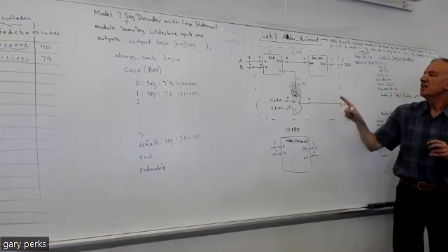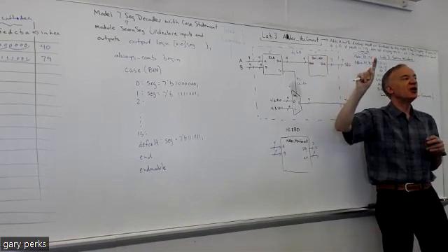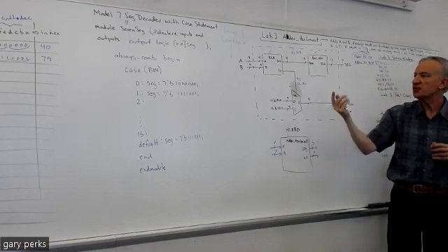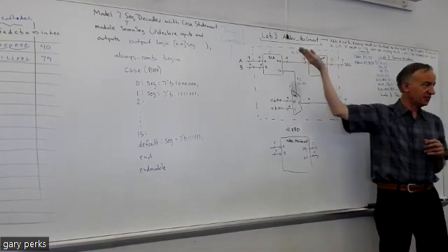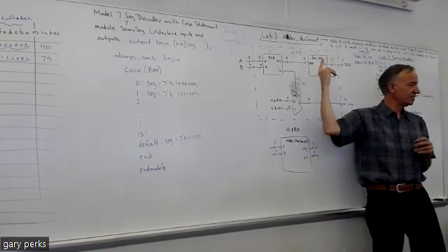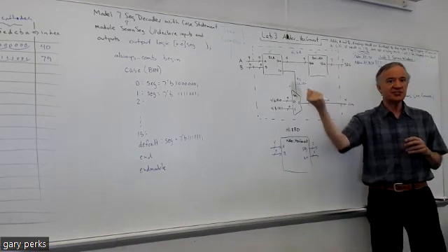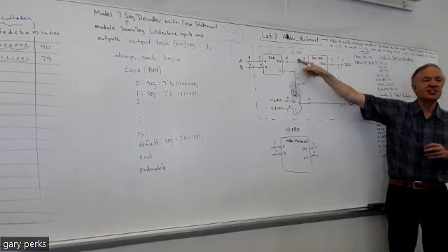Oh, the other thing is, because the internal signals for the RCA were all a single bit, right? When you declare your internal signals, and remember the way you do that is after you declare the inputs and outputs for the overall structural model, then you do logic. You define your internal signals with logic. Okay, well, what's different about this internal signal? It's 4 bits. Yeah, it's 4 bits.